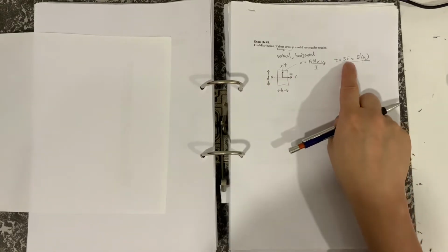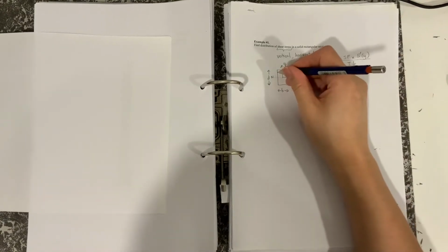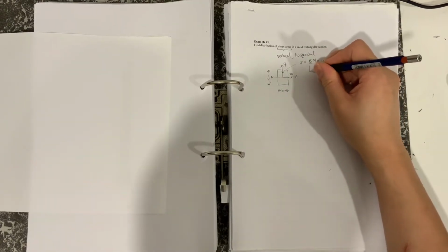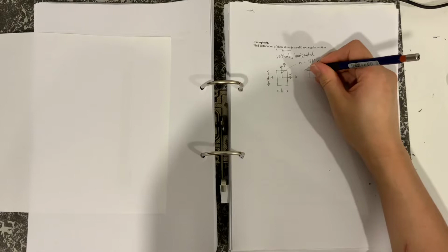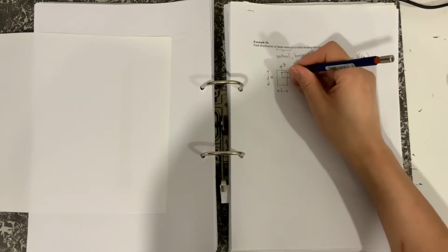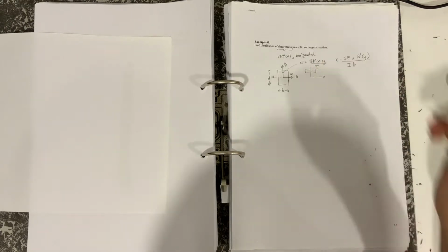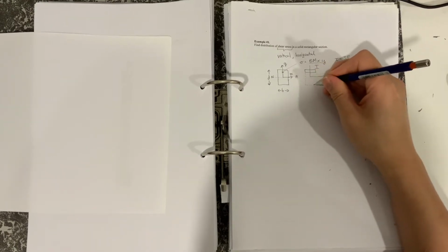So let's try and decipher this. The shear force is from the shear force diagram, like the BM is from the bending moment diagram, and this is the first moment of area at that height y. So what it means is, I'll draw that out again, and this time I'll draw at that height across there. I'm not going to be drawing the whole section, just that bit there. The rest of the section you could pretend was in dashed lines.